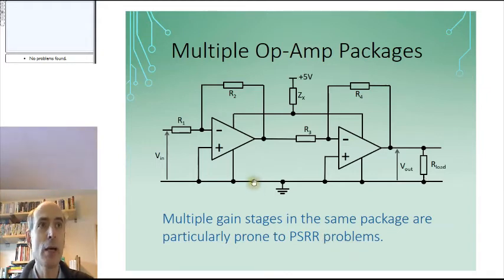Whenever you have a lot of gain distributed between two different op-amps, it is always a good idea, if you can, to make sure that those two op-amps are in separate packages with their own power supplies.